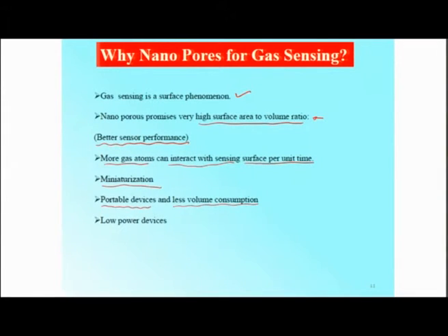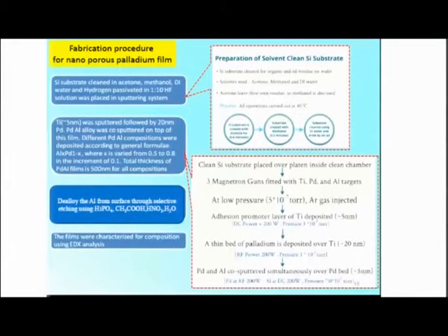And so, because of these small volumes and small sizes, obviously these are low power devices, the requirements are very small, and we can see what strategies are being utilized for fabrication. So, in the first strategy, we have developed a highly nanoporous palladium film, and this paper was also published some time back in Sensor Letters, where we showed substantially high repeatability as well as very low sensing and baselining time for the particular sensing element.